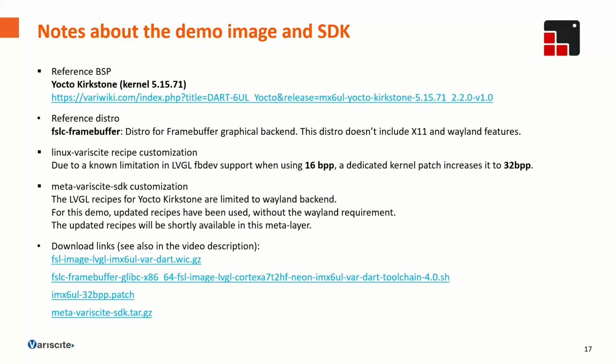This is not a real software-side requirement, because actually LVGL has been designed to work directly on the FrameBuffer. But this is how the community tested, and they were fine with this. Trying to limit the use of resources, we introduced specific changes to the recipes in order to work directly on the FrameBuffer. By the way, these changes will be published in our meta layer, and we will also reference it in the video description that you will find on YouTube.